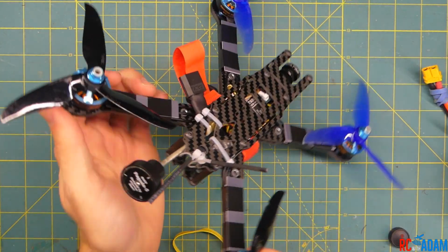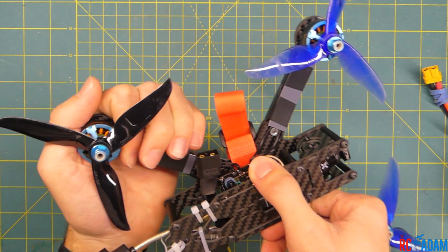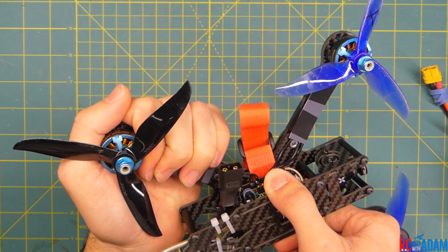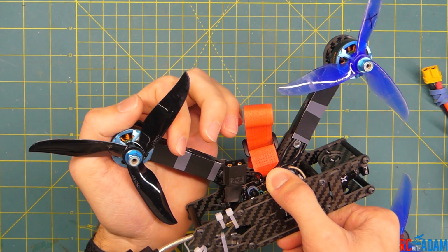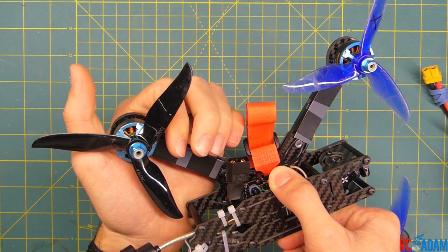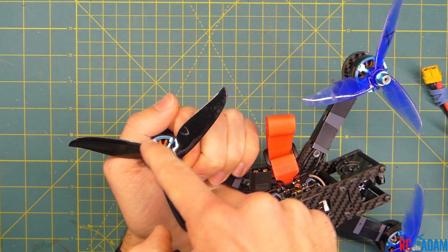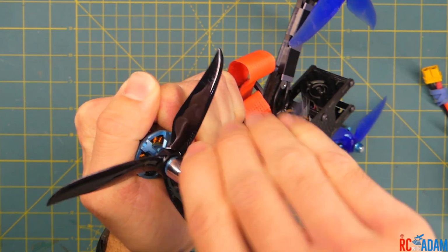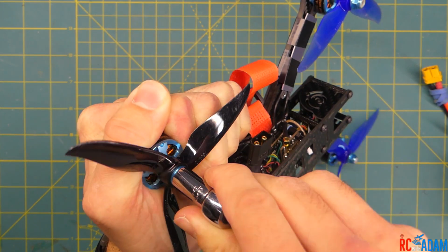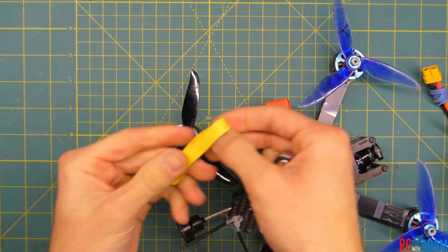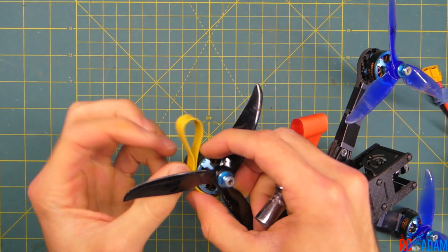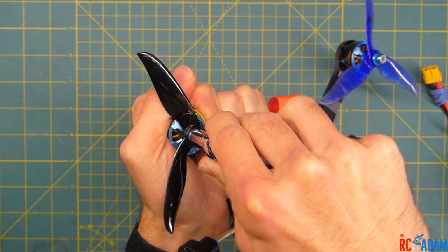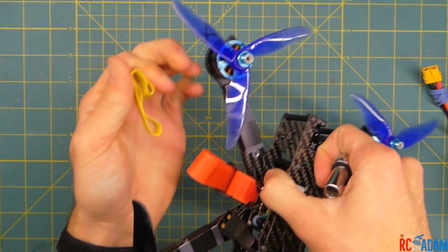Now here's a little tip for when you're tightening these down. What I found works really well, unless you have motor guards or something, I like to grasp them like this. So I'm wrapping my thumb around the motor and pinching it between my first finger, and that way I have a lot of contact with the motor, and I can hold everything steady and in place as I'm tightening it. And if it's still slipping out of my hands, I'll just take a rubber band and put it around the motor housing, the motor bell there, and then tighten it down and get a better grip.